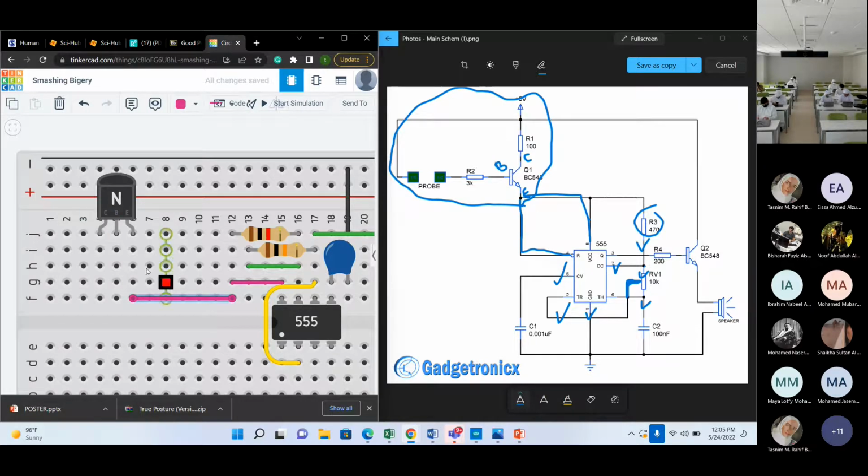Are you all done with this connection here? Excellent. Now let's connect the emitter to pin number 4. Where's pin number 4? This is pin number 4 here, right? Our reset pin. So I'm just going to take a wire from here. I'll bend it here, and then here, and then here, and take it all the way here. Then I'll stop it here, bend it once again and insert it into one of the holes. Is this fine?